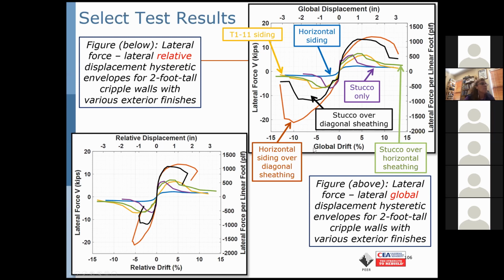And it highlights the fact that we did see sliding of the sill relative to the foundation, due to the fact that these existing, unretrofitted specimens were fairly lightly anchored. I won't go through all of these details, as we've got a strong family of reports which attempt to document all of this, but some useful remarks when cross-comparing these various finishes.